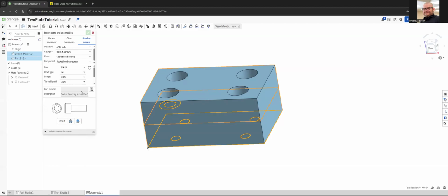And if you get an entire machine and you're showing all the screws, those surfaces take time to render, and when we've got hundreds of screws in a machine, just the screws can really, really slow down an assembly and slow down SolidWorks performance. So I prefer to model my own and use cosmetic threads, just because I don't see a real reason to show all of those helixes, right?